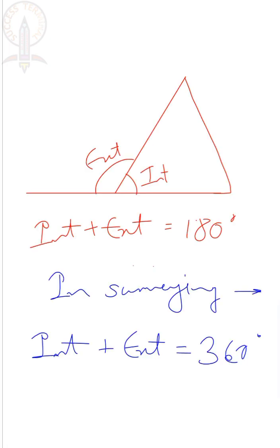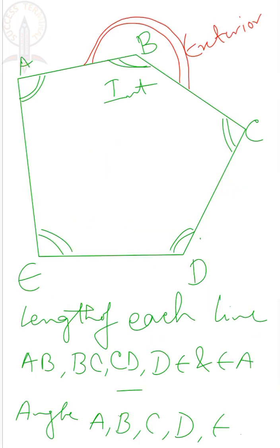Now we have to understand the basic principle of compass surveying, that is traversing. And what is the specialty in case of traversing? Traversing is to enclose an area in terms of straight line. It may be a closed traverse or it may be an open traverse, but what you have to consider is the length of the line, that is here AB, BC, CD, DE, EA, length of this line. This data is very important. And the angle, that is angle BAE, AED, EDC, DCB, and CBA in this way.